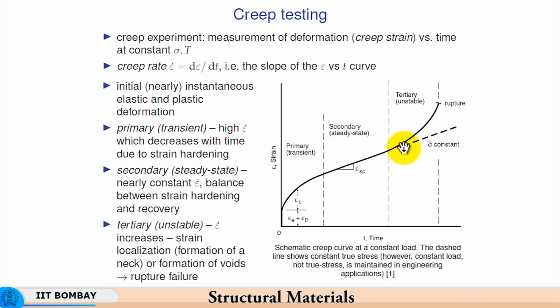So, as the cross section gets depleted, the strain rate continues to rise, and as the strain rate rises, the cross section starts further reducing in magnitude, and the stress continues to rise. So, this becomes a vicious cycle, and due to that vicious cycle, the rupture becomes faster. Now, just one comment here, this creep curve was constructed at a constant load. So, you had a constant temperature and a constant load. Initially when it was loaded, it showed during primary transient relatively large strain, and then it settled down to one particular slow strain rate creep at that particular stress level.